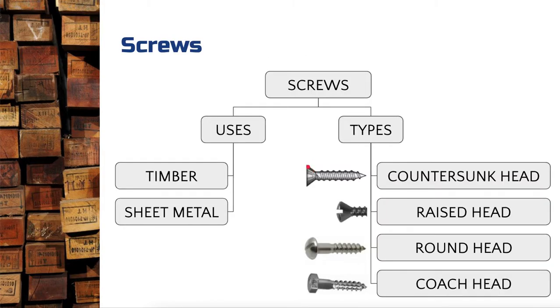You've then got this sort of little dovetail point that I mentioned. That's a specific shape. And what happens is when you plan to use a countersink screw, you actually need to drill out a small countersink hole so that that V shape can actually fit in. Otherwise, what happens is it will try and compress your timber. And if your timber is too hard, it will split it. So you actually have to pre-drill a pilot hole for the shank, but also pre-drill a countersunk hole for the countersunk head to fit within.